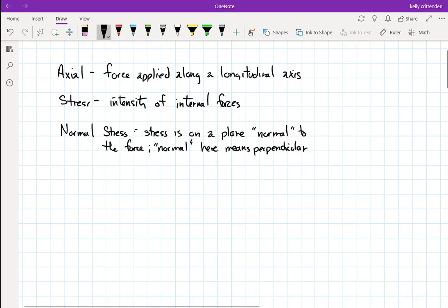The general idea is that you calculate this normal stress or axial stress, and you compare it to the material strength, and that'll tell you a factor of safety. If your factor of safety is 1 or greater, then you're okay, at least under those exact circumstances where you calculated that. If it's less than 1, then you probably have some chance of failure in your part. Failure might just mean that it stretched out some. It might not necessarily mean that it broke, but for a lot of machines and buildings, if they stretch too much, that's also failure, whether or not they catastrophically busted into pieces.